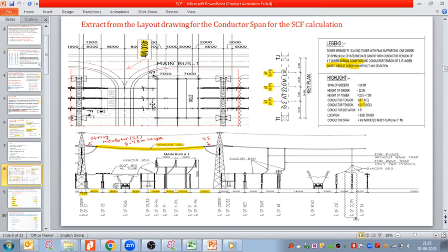So I have worked on one project which had a 500 kV substation, the same as 400 kV. Each and everything we designed the same as 400 kV. Okay, so this is my line side, and in 500 kV we have followed the same 1.5 breaker scheme. So this is my line side country. Hope you are understanding about this layout and this portion.